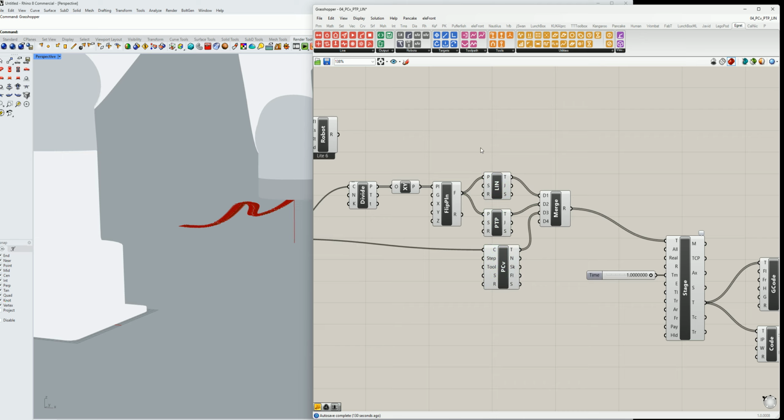But do we really need all those points? So if we had a straight line and we said divided by 10, we don't really care about the 8 points in between. We just need to know the start and the end position, and we don't need to cumbersome the controller with all the in between points. There is an option to use a reduce path. It's also in the toolpath and hitting reduce. We could drag this into here, and you can see our toolpath did reduce a little bit by a third, and it should have the same